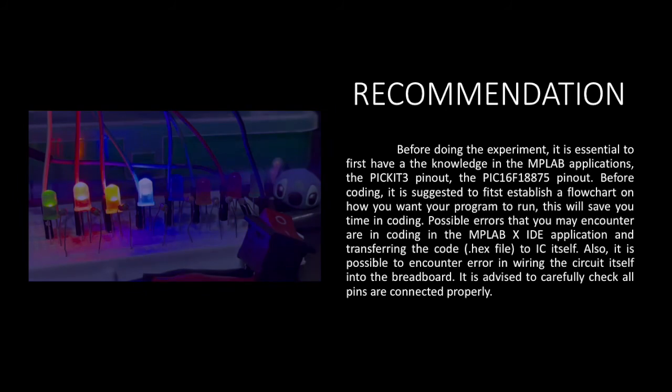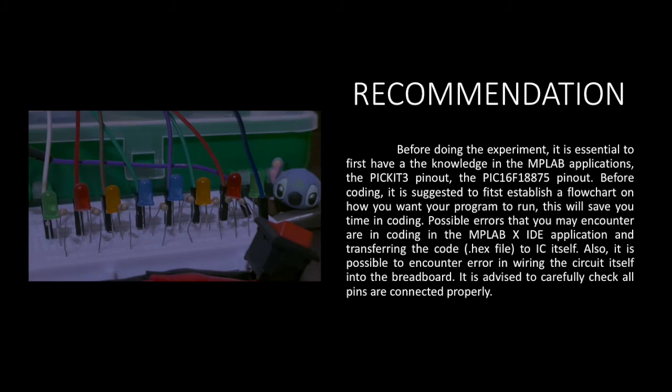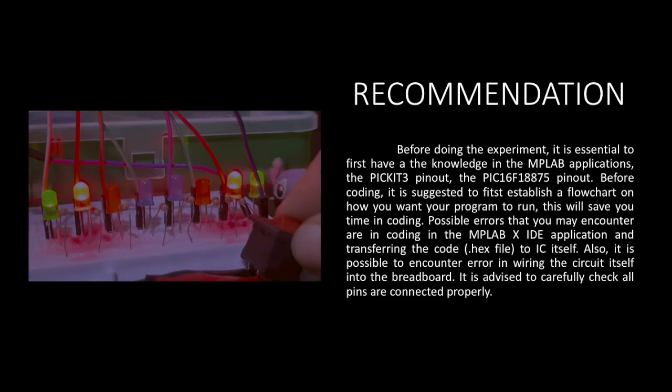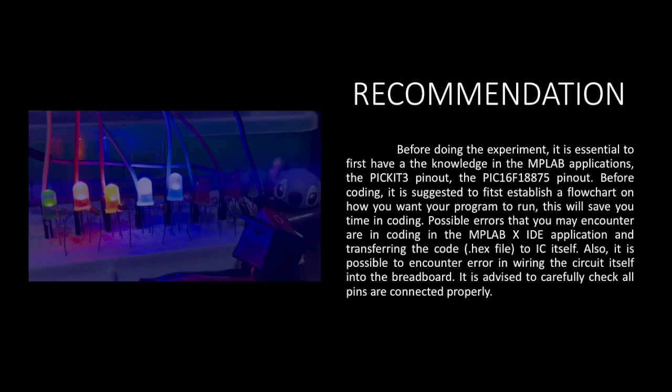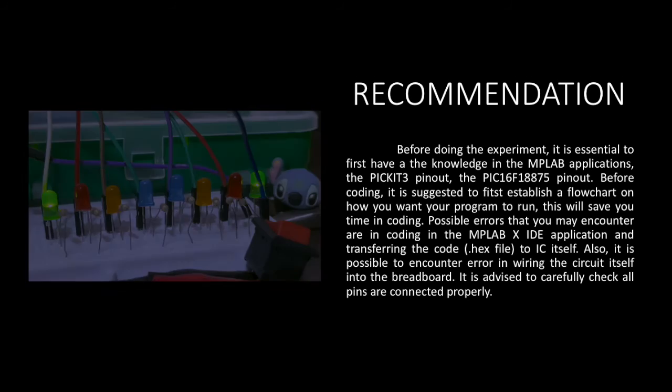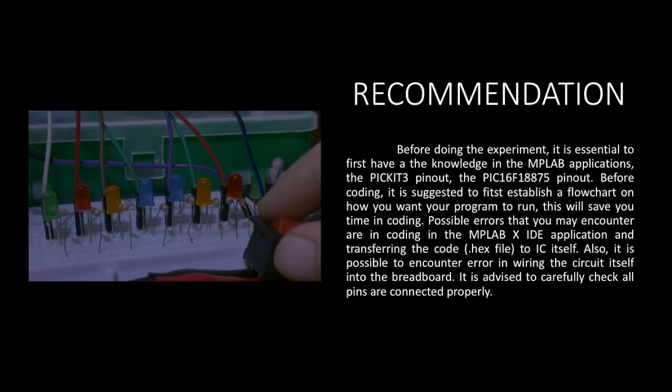For the recommendation, before doing the experiment, it is essential to first have knowledge of the MPLAB applications, the PICkit pinout, and the IC pinout. Before coding, it is suggested to first establish a flowchart of how you want your program to run. This will save you time in coding.